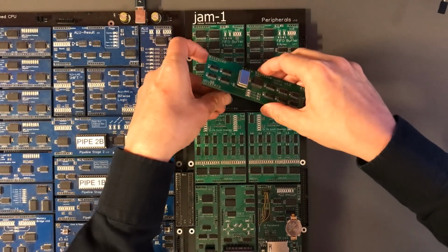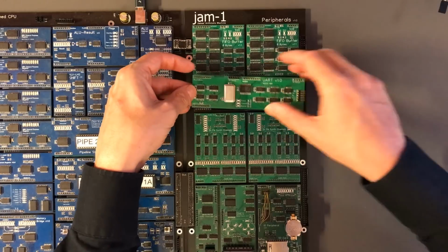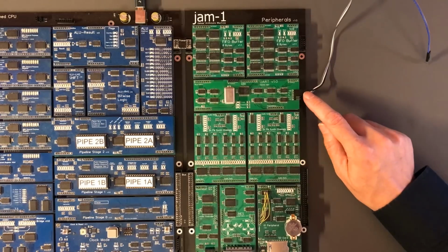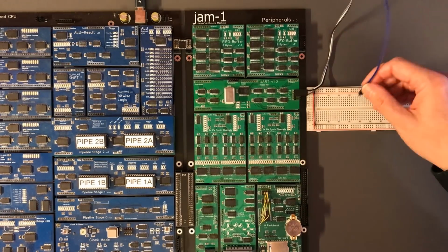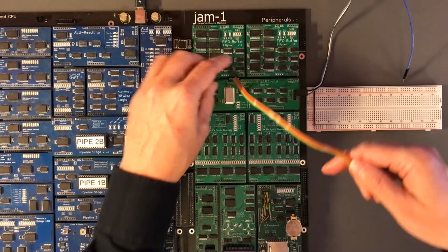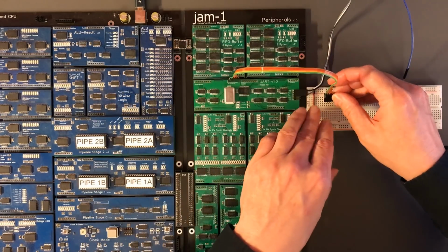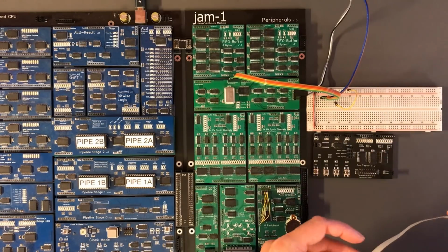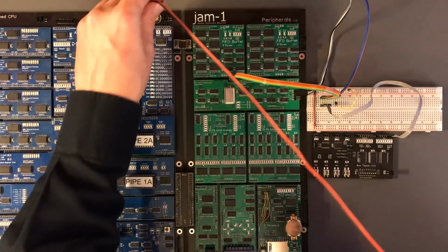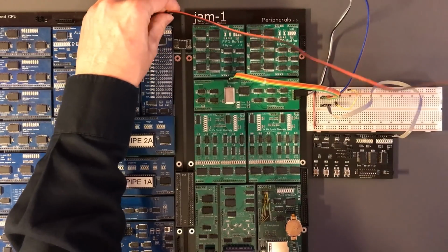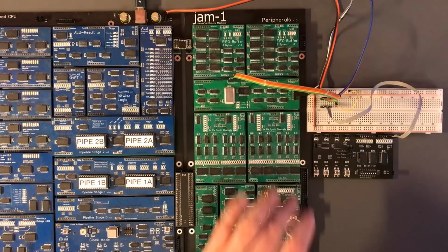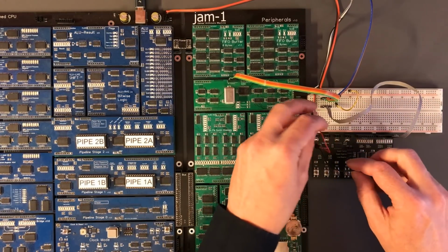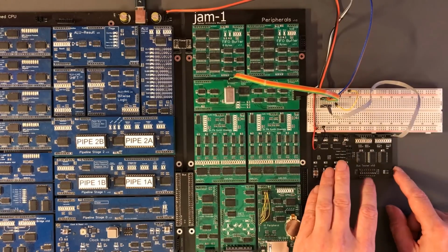Alright, let's get the board back in. Need to connect that to clock line. It'll be really nice when the new PCB doesn't need me to do that manually. Connect the ground, TX and RX lines. It should be ground and then the 4 bits of the receive FIFO count. Let's pull that low. First up, I want to confirm I'm actually getting the right data out of there. It might be easier to use this power line at the top. Daisy chain some power to my little tester here. And at this point, I'm just going to be using this for some easy LEDs.